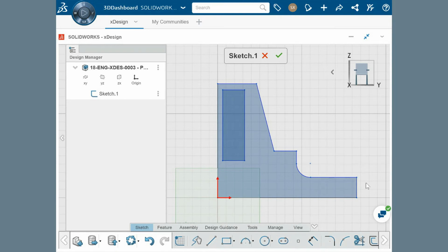I quickly want to mention that you can see the sketch constraints existing in the sketch simply by clicking on a sketch element. So if I click on this line, the icon appears on screen, letting me know which constraint type has been applied. If needed, this constraint can be deleted either by selecting it graphically and pressing Delete, or by clearing it in the context toolbar.